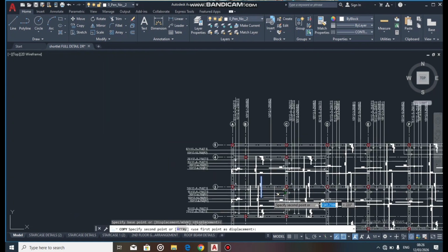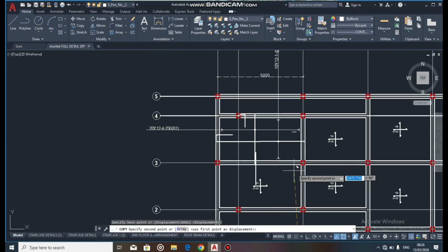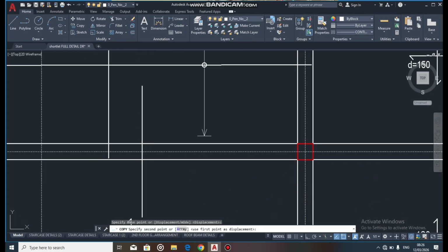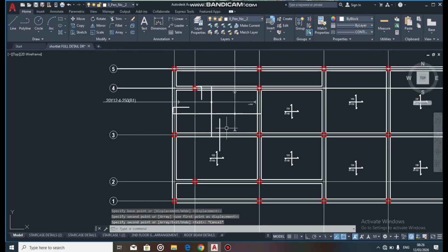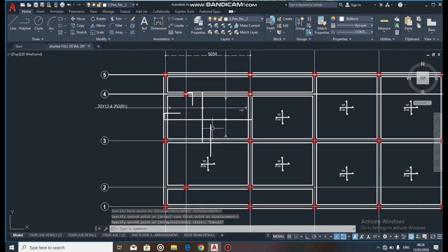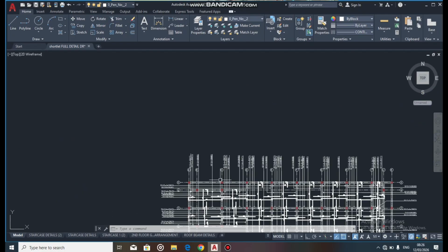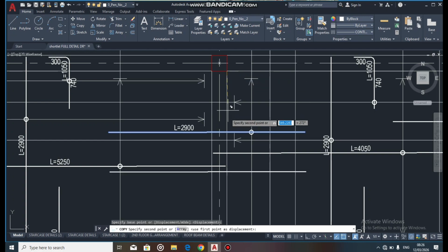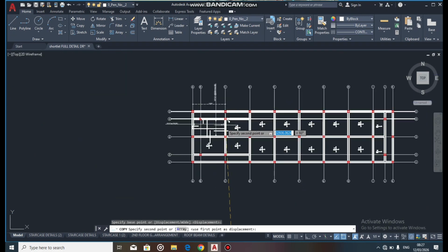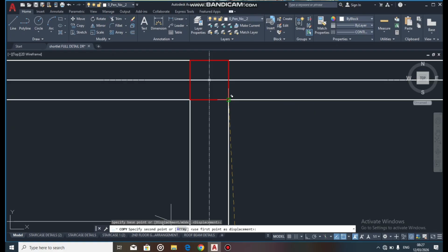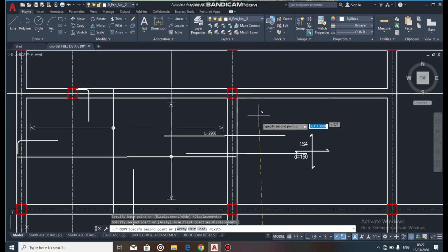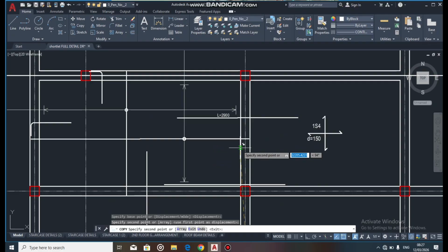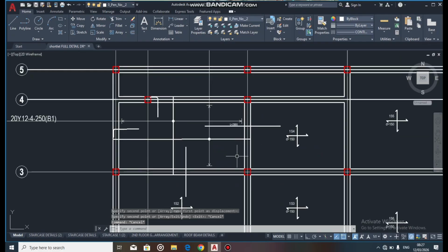You will also detail it for the continuous edges. We have your bar running across the two panels like this, touching this side of the above panel and the bottom panel. That is the top bar to take care of the moments at those continuous edges, right? So our right hand side is also continuous, so we also have our top bar running across both panels.